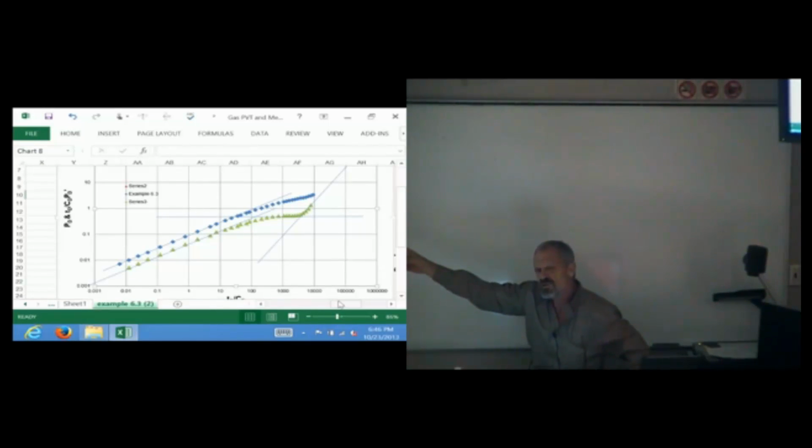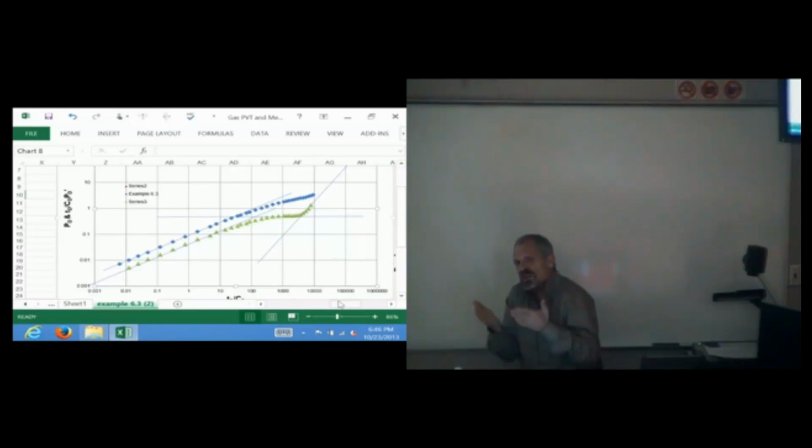You see, I have two flow regimes that are prior to boundary dominated flow and after wellbore storage. So the wording middle time region is leaving normal usage. Middle time region means you're looking at radial flow, because there's only one region between boundary dominated and wellbore storage, radial flow. But here's an example of where between the two you have both radial and linear.